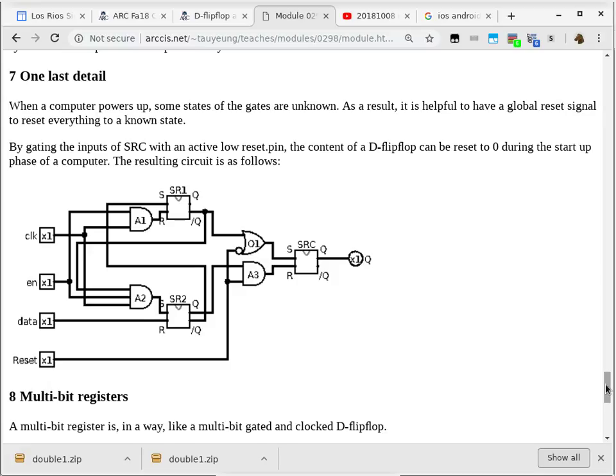Okay? So the supervisor chip has what we call a watchdog mechanism. A watchdog mechanism is kind of like a dead man switch. So the watchdog mechanism says, okay, I'm making this assumption. When the system is healthy, somebody is going to give me an "I'm still good" signal every, let's call that 5 seconds. So every 5 seconds, I'm expecting the operating system to confirm with me that everything is still good. Let's say 5 seconds, 10 seconds went by, and I did not get a confirmation that everything is still good. That watchdog is going to go off.